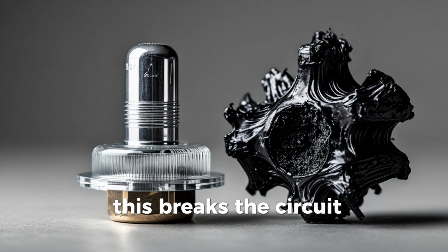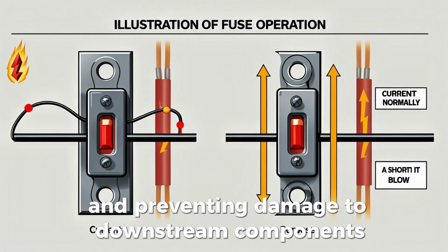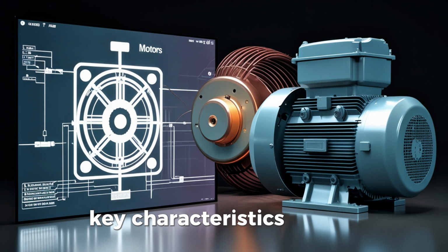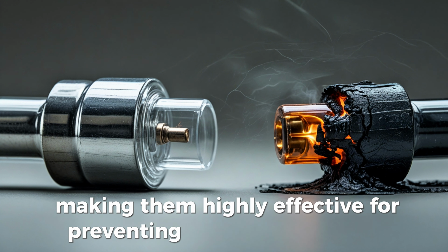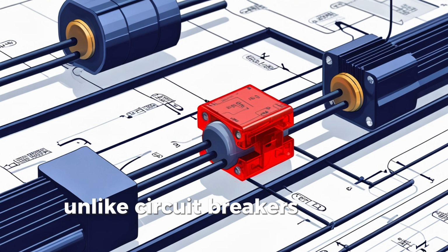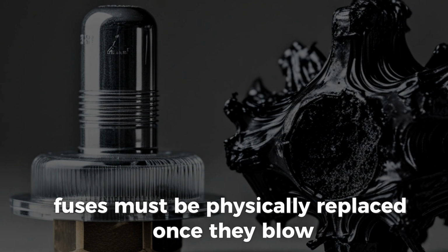This breaks the circuit immediately, stopping the flow of electricity and preventing damage to downstream components like contactors, overload relays, and motors. Key characteristics of fuses. Fast-acting protection. Fuses react almost instantly to fault conditions, making them highly effective for preventing equipment damage. Single-use devices. Unlike circuit breakers that can be reset after tripping, fuses must be physically replaced once they blow.